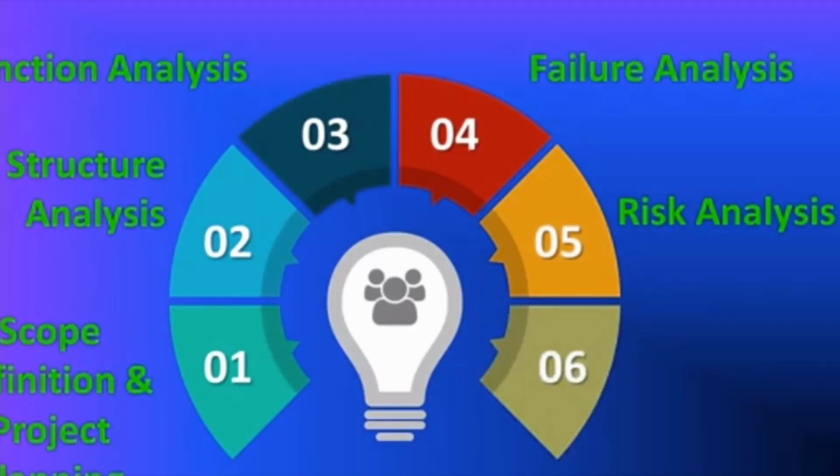The sixth step in the process is optimization. Its purpose is to determine the actions to mitigate the risk and assess the effectiveness of those actions, and reassessment of the actions. In this revision, the change is done in the recommended action column. Now it is split into 2 columns for capturing preventive action and detection action.